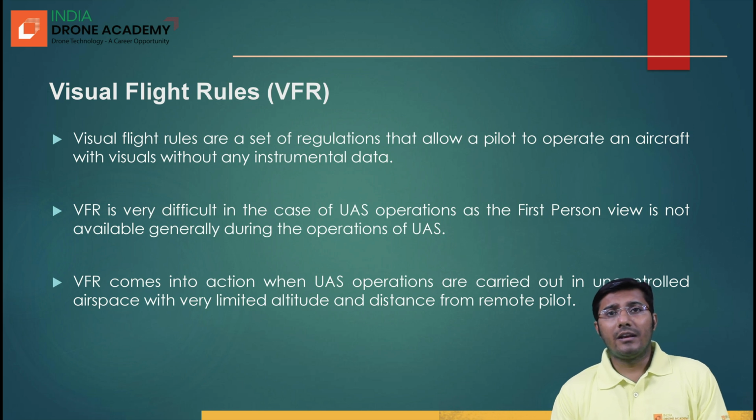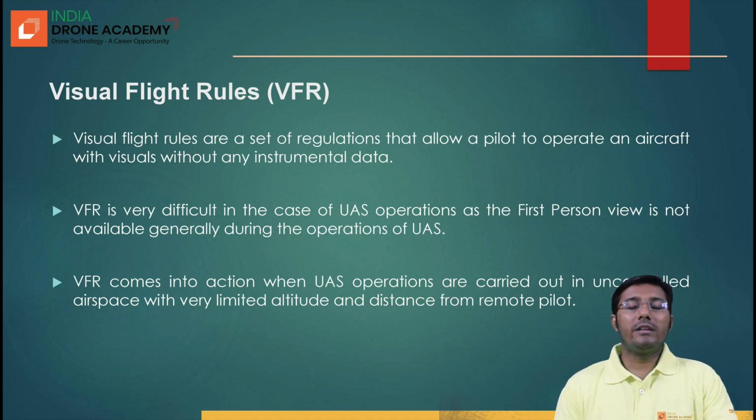first of all, the aerodrome control service will take care of the aircraft before takeoff, and after the safe takeoff, it will hand over the responsibility to the approach control service. Then the approach control service will hand over the responsibility for the safe operation of that aircraft to the area control service of Mumbai. When the aircraft crosses the area control service, it will enter the flight information region of Mumbai, and from there on they will take care of the aircraft's operations.